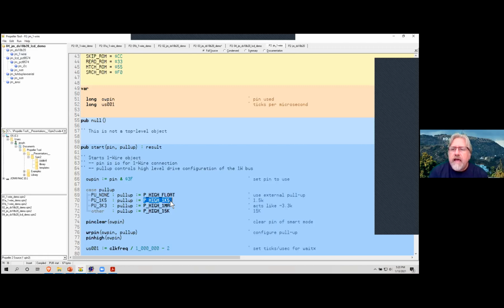If you download it to Flash, we're actually using 3 bus topologies in the program. Now, we haven't talked about SPI. We're going to do that in a future class if people want to keep doing this, because the SPI bus is used by the Flash, and then we have the 1-wire bus to talk to the temperature sensor, and we're using the I2C bus to talk to the display. If we were outputting to the terminal as well, then we would be using yet another bus topology. It's kind of interesting, all these different communication things in one project, bringing it all together, making things work nicely.